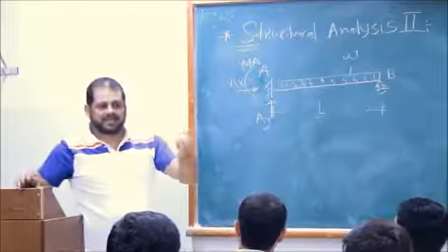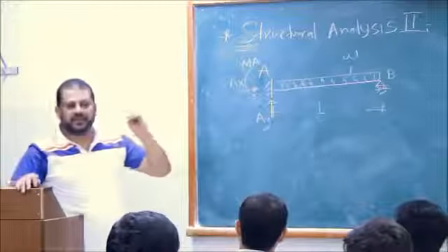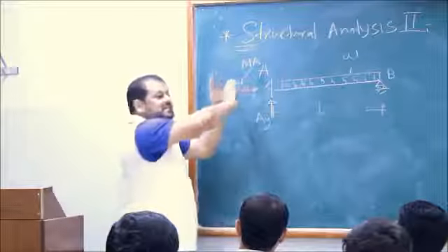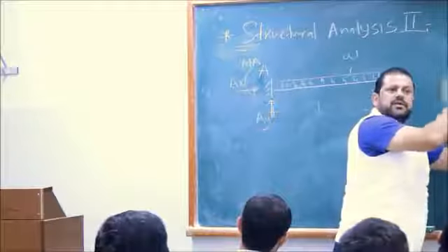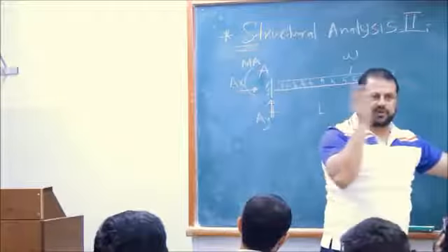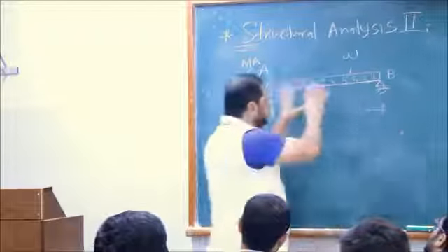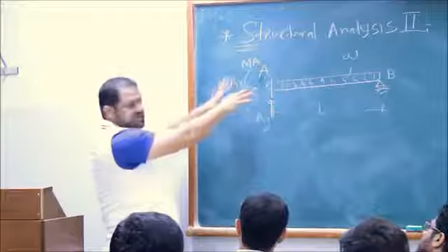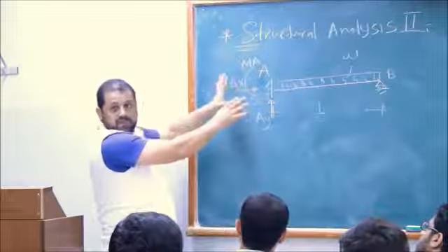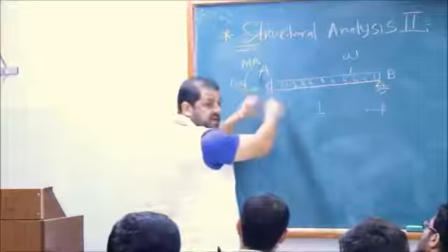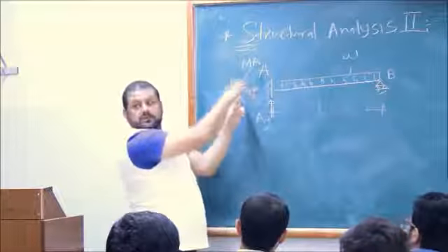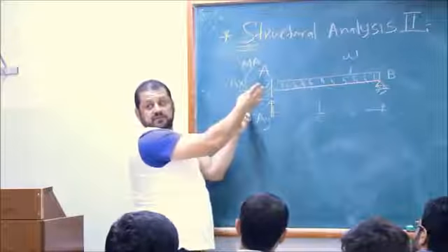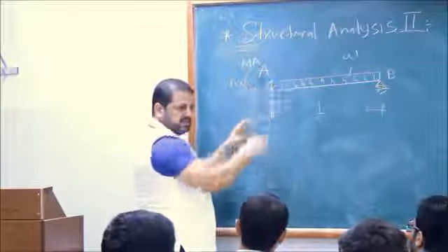When you find the reactions, these directions have nothing to do with the sign convention you covered in structural analysis 1 and statics. Is this a positive moment or negative? That's different. Here, just: what's the reaction, and what's its direction? Once you have them in the right direction, if we get this one negative, it means it's in the other direction. Put it positive in the other direction. Put everything in the same. Go ahead.